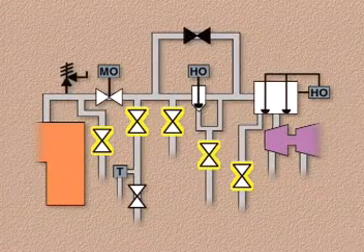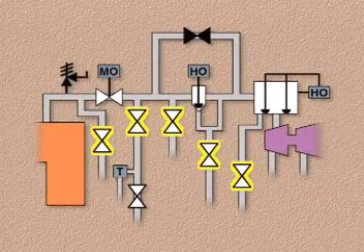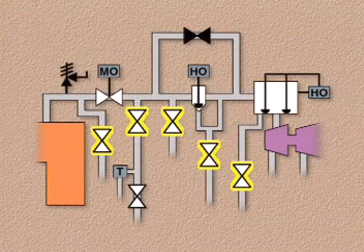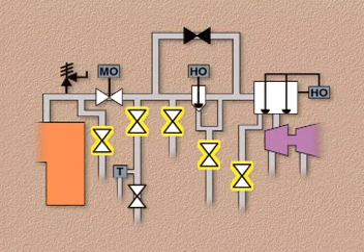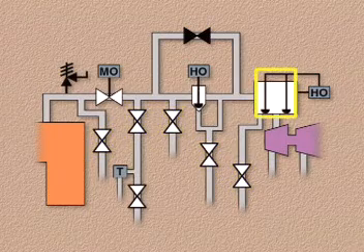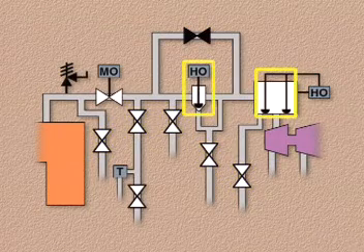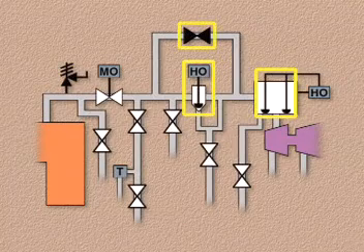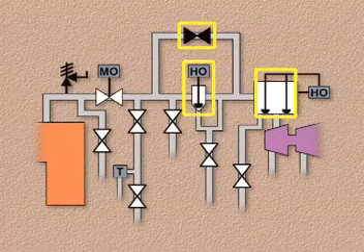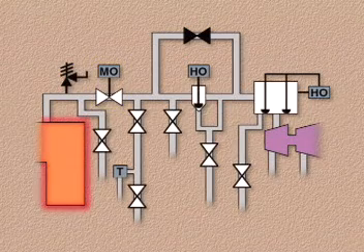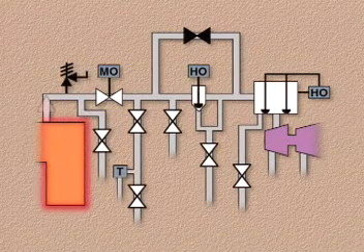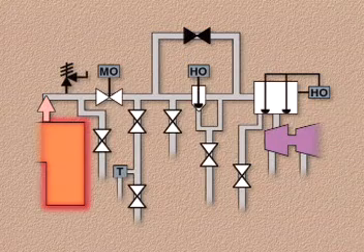The drain valves begin in the open position, since the drains for removing accumulated condensate from steam systems usually remain open during the entire period that a plant is shut down. The turbine control valves, the main steam stop valve, and the main steam stop bypass valve are closed. The boiler stop valve is opened. After the boiler is fired, steam begins flowing through the main steam system.